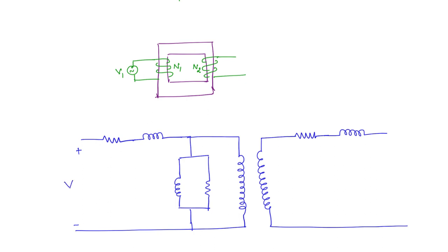So here first we will mark the voltages and the parameters. This is the primary side voltage. In some textbooks they use V1, or you can also write it as VP. P means primary side, but we will use both of them interchangeably. Now this resistance we will take as R1, this inductance we will take as the reactance X1, and the current we will take as I1, okay.